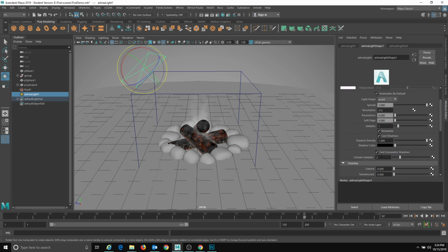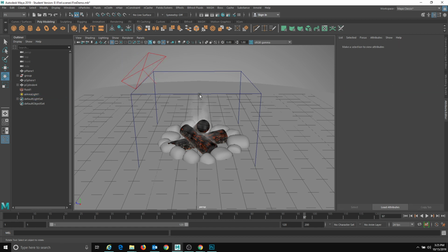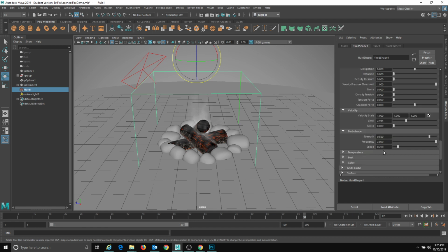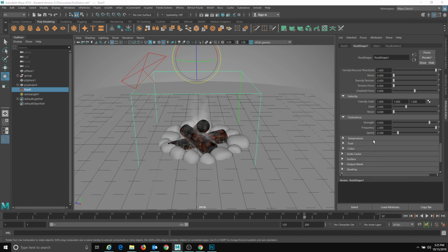We are now at the point with our area that we can go into temperature. I'm going to turn that up to 2. And I'm going to change my buoyancy to 14.6. And let's see what else we got to do here. I have my dissipation at a 0.48 or 41, so maybe around here or so.